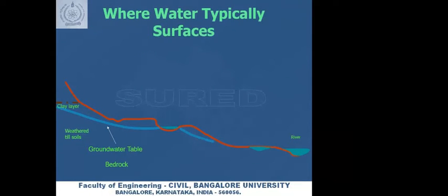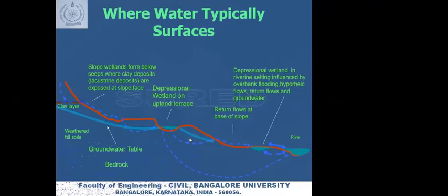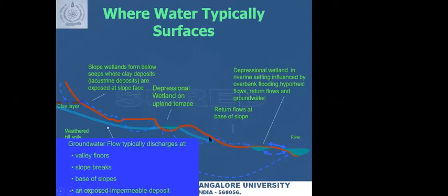Now, to make what I talked about clear, we can see that whatever precipitation occurs in the uplands enters the ground, and in the subsurface flow, sometimes it may reach the groundwater table. Some portion of the water seeps out in the foothill. So here one can expect a wetland, particularly in this portion. Next, here you are getting groundwater, and here we are getting surface water or depression storage, and again in these portions one can expect a wetland. So, with simple line diagrams, one can expect groundwater-contributed wetlands, along with other percentages of water source, maybe from precipitation or from the river, that is surface water.